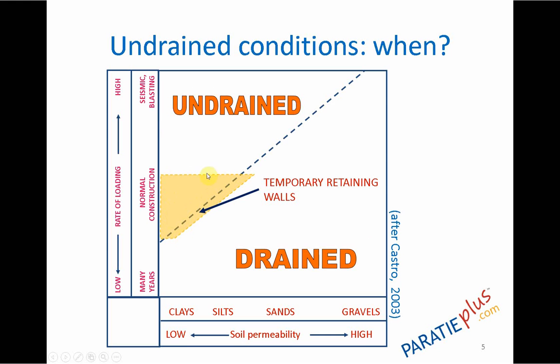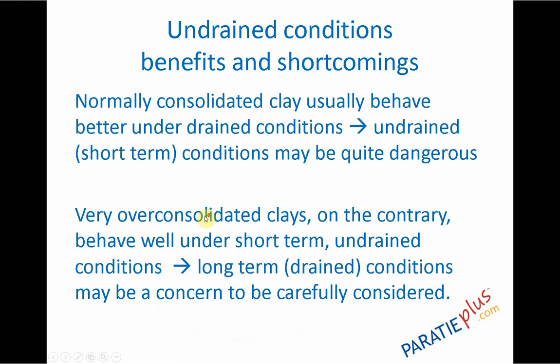But for retaining walls in clay condition, we are here, or almost here, in this situation, and normally we may consider that undrained condition holds, but we may sometimes exceed the time where the structure may stay in this condition, and so we may go to drained condition.